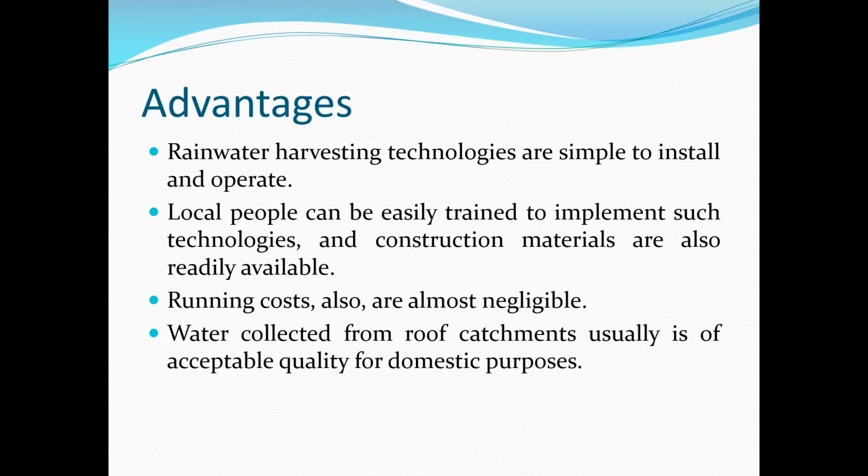Now, the advantages: rainwater harvesting technologies are simple to install and operate. Local people can easily be trained to implement such techniques, and construction materials are also readily available. The running cost is almost negligible. The water collected from roof catchment is of acceptable quality for domestic purposes.